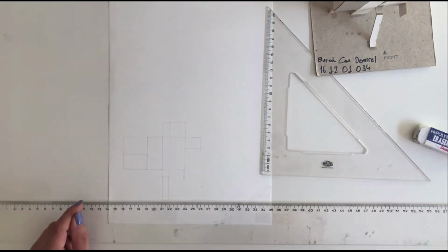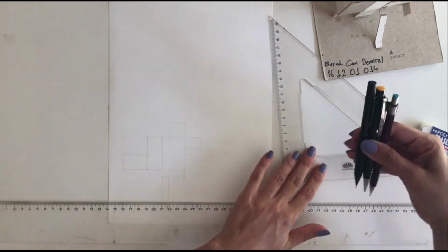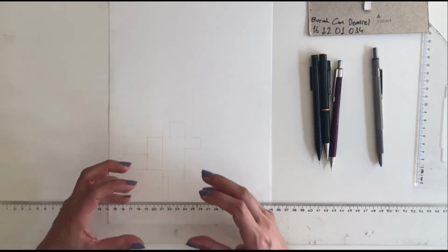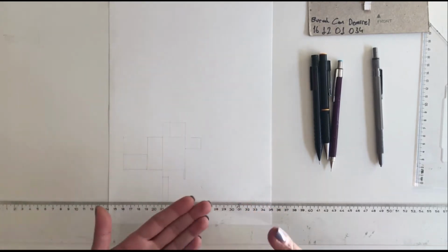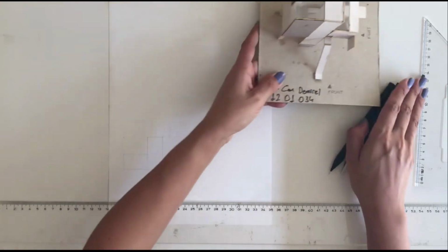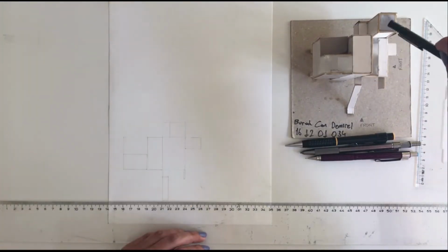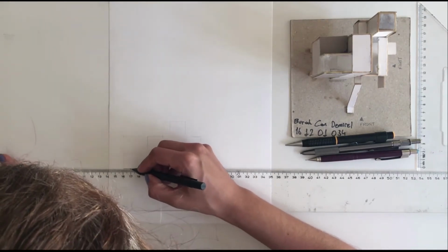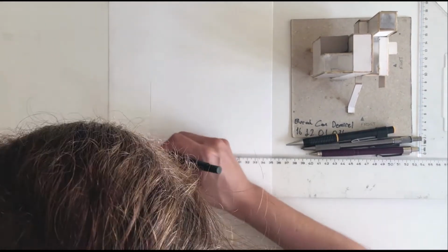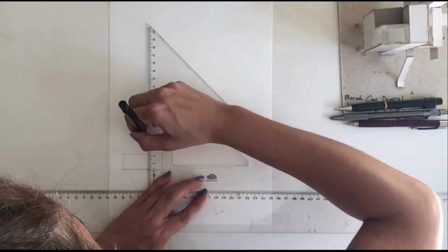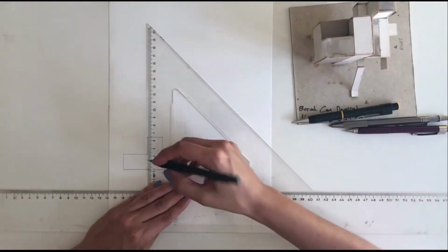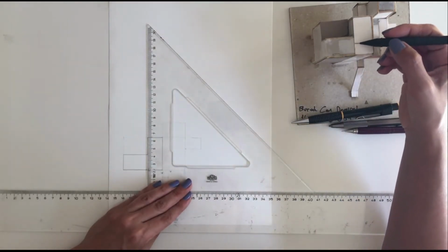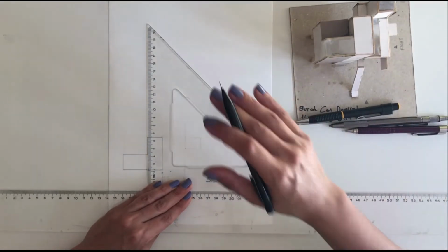But now I'll take some mechanical pencils and also this lead holder. Now what I'm going to do is make these surfaces readable, showing which are on top and which are lower surfaces. These surfaces, 3 of them, are on top. So I'm going to draw these surfaces with thick lines. I'm not going to draw this line with a thick line because it's only a change in the material. It's not a change in the height of the object.